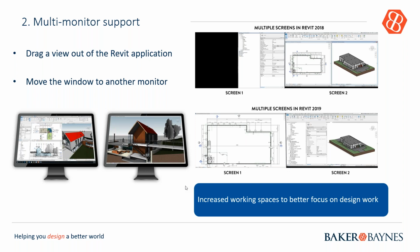So what you have now is you can have your 3D model on one screen and a floor plan on the other screen, and you can see both of these simultaneously. Again, the way you would do it is you would drag a view out of the Revit application and literally move it to another window or another monitor. I've got a video on this, which I'm going to play.